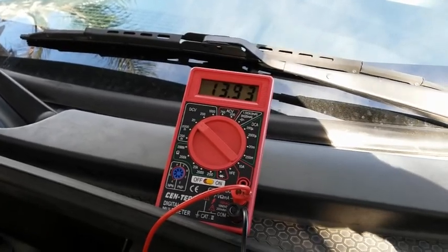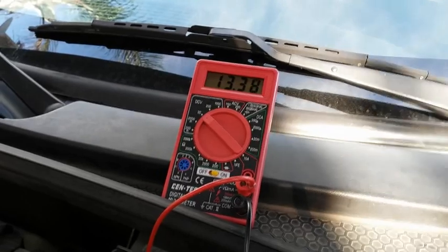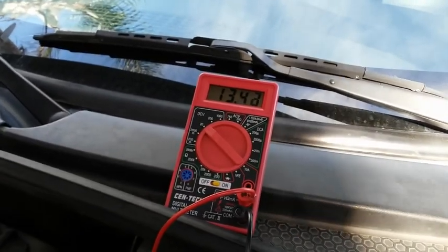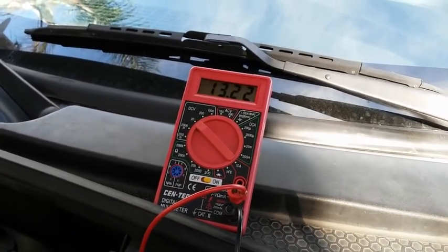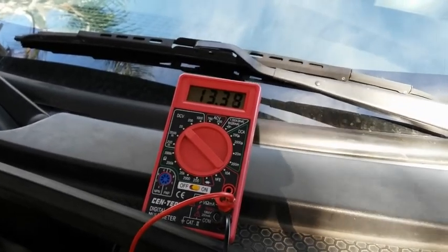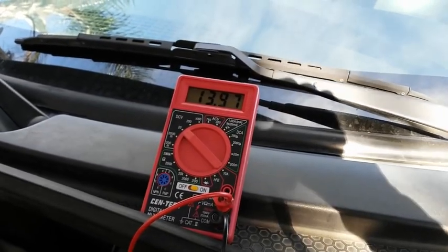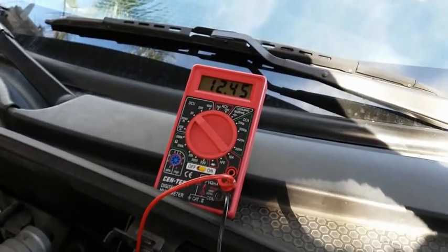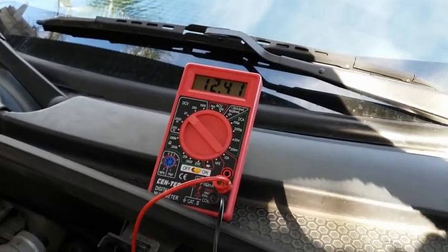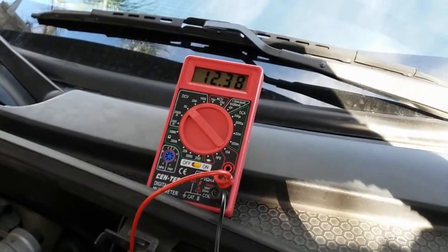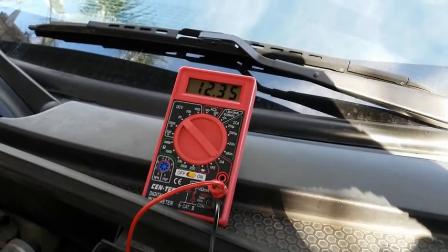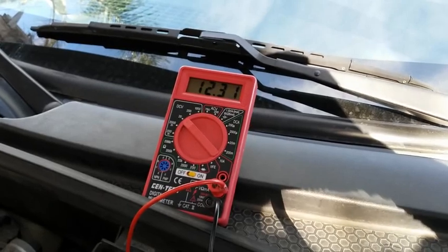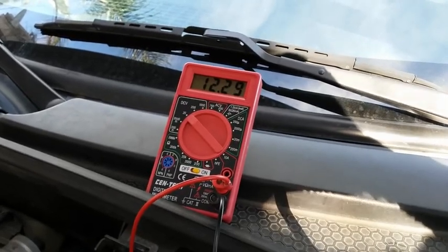Alrighty, so the next step is to turn the engine off and then watch our voltage. And hopefully after 90 seconds, this battery voltage goes back to approximately 0 volts. Alright, so with the key on, engine off, our signal wire is showing about 12.38, but as you can see, as the seconds go by, it's actually going lower and lower.